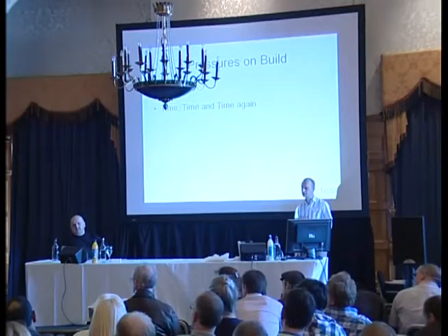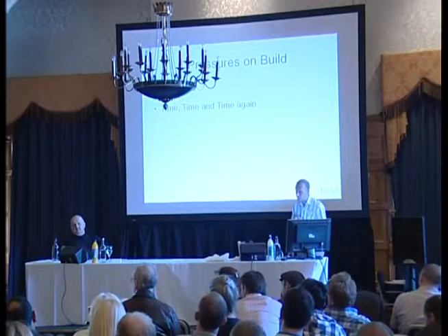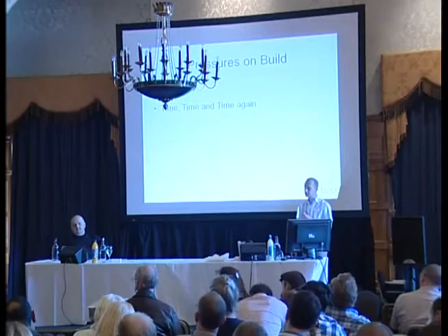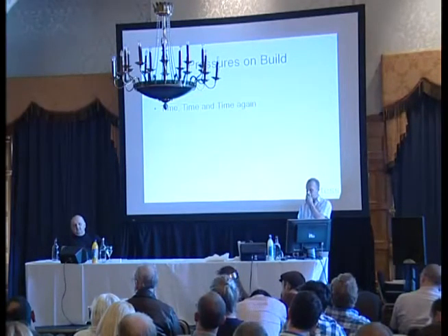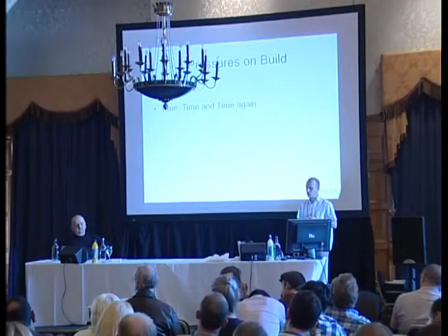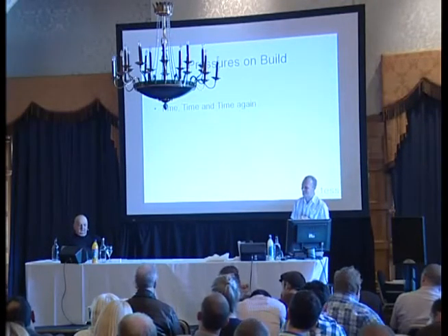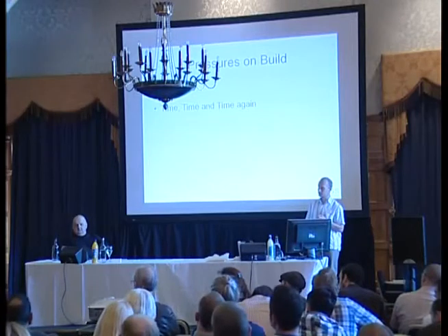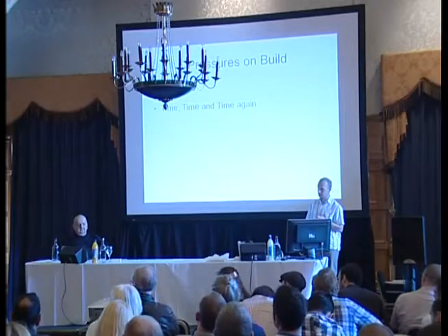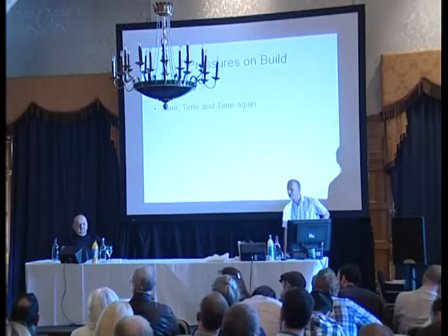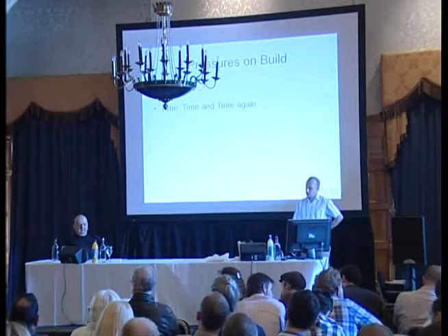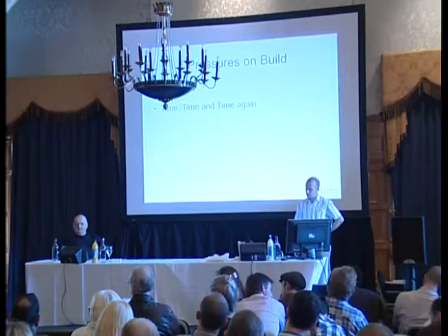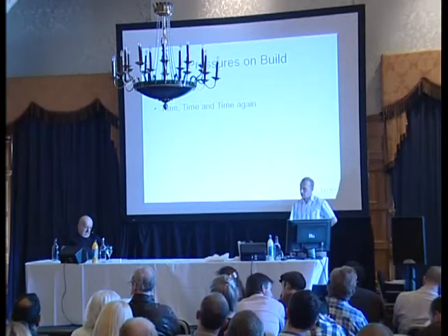Sorry, what's on that? You know the picture you showed earlier with the water ballast, the stage system on a steel deck or a hanger deck type structure. Yeah. But there you've got three different elements that are all structural, that all come from being matched together. Cobbled together, I think would be the best term. You've got three designs between all those three products. One's being used for something that's never designed to be used, which was ballast, and the other two are designed to be put together. Yeah. And there you need another design really to show all those three things working together as one new structure. And that's what we don't see.